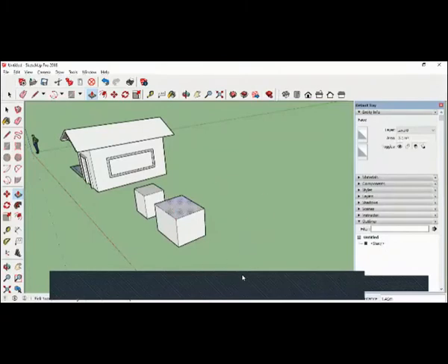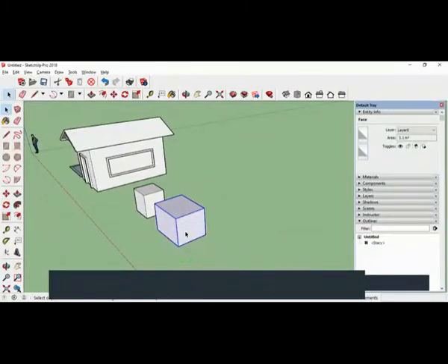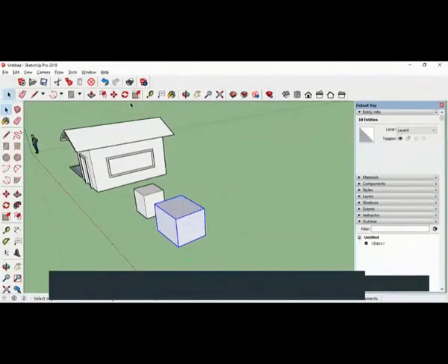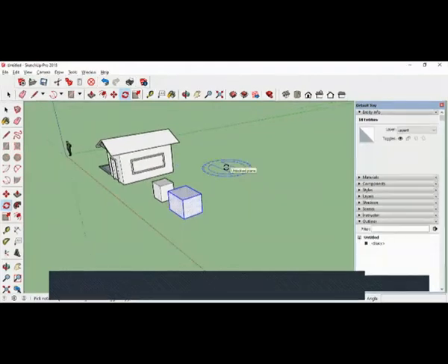You want to rotate like this? Then select rotate. Click here. You have to select the full object, otherwise you will be selecting only a portion. 3 times you click, rotate, click. You can see it rotate like this. So whichever angle you want, you can rotate by going to that particular face. So that's how you use the rotate command. You can try that. I hope you got some idea now.